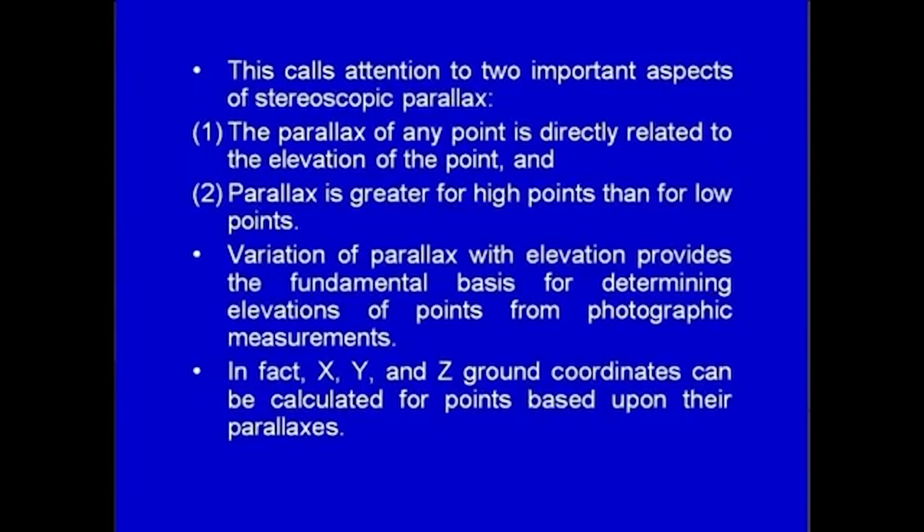So, this calls attention to two important aspects of stereoscopic parallax. First, the parallax at any point is directly related to the elevation of the point, and number 2, parallax is greater for higher points than for lower points.